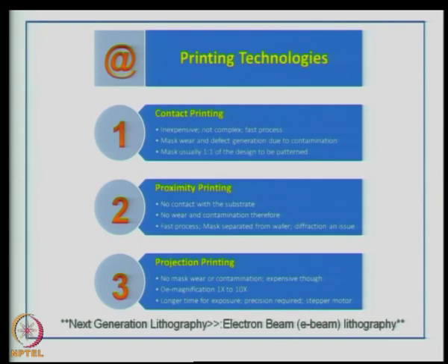But we, because of the demand for fine lines, might be seeing these kind of printing processes coming into this industry as well. But the next generation lithography in the semiconductor industry especially is to use electron beam lithography, because we are moving towards fine lines.